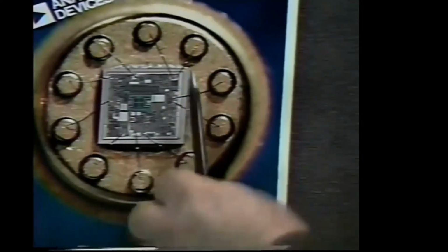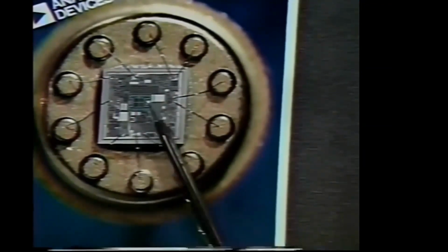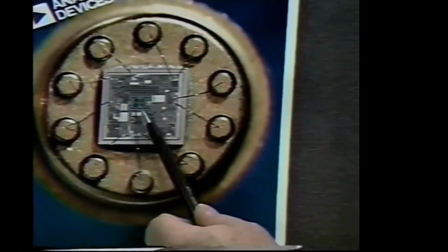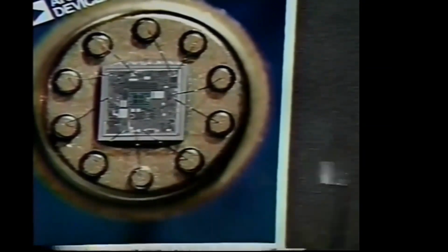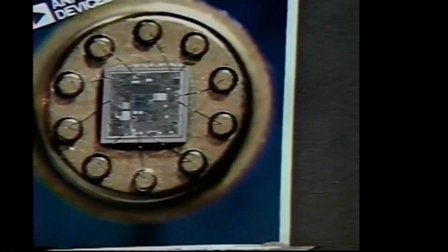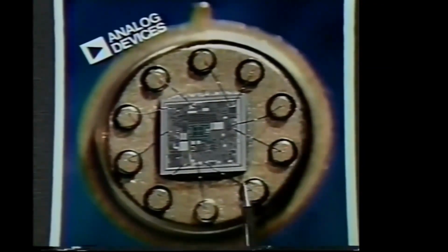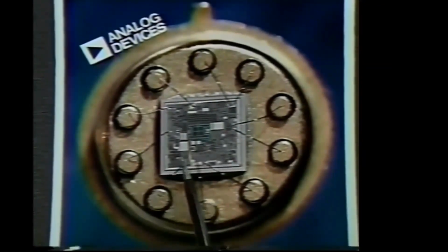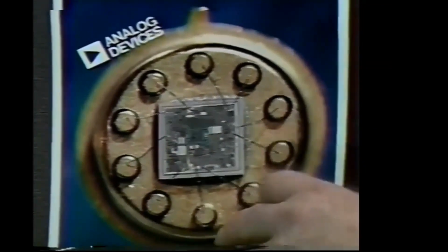The system was realized again in 1991 and is shown here in the original package in which it was sold. Again, it's a complete monolithic chip. At the very center, you can see the exposed sensor, which I'll show you ever more close-up pictures of as we go on. It's in a 10-pin package, again, to accommodate the gain requirements of the variety of users. And it has something which you may or may not be able to see. It has trimmable thin film resistors. This whole chip can be calibrated at the wafer level.